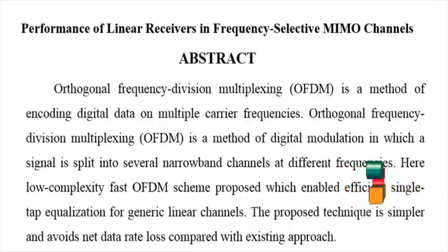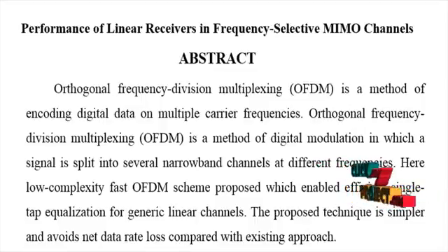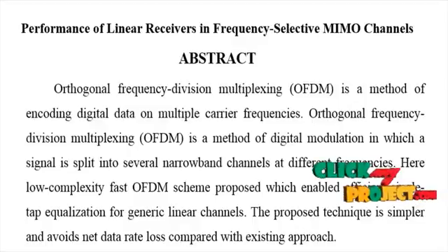A major design challenge for high-speed broadband applications is the time dispersive nature of terrestrial radio channels. The effects of multipath propagation can be analyzed in the time domain or in the frequency domain. In the time domain, when the channel is longer than one symbol period, the interference among consecutive transmitted symbols, known as ISI, distorts the received signal. In the frequency domain, if the communication bandwidth is larger than the so-called coherence bandwidth of the channel, then distinct frequency components of the transmitted signal will undergo different attenuation, resulting in distortion.